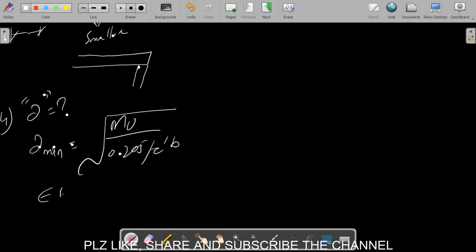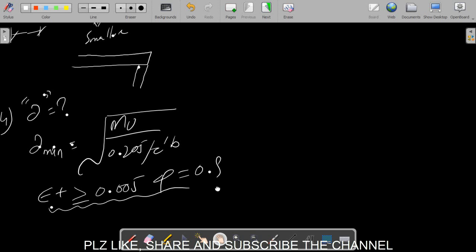When we want to ensure epsilon t should be greater than or equal to 0.005 and phi factor is 0.9, so if you want to ensure an under reinforced section, the minimum depth will be this one.